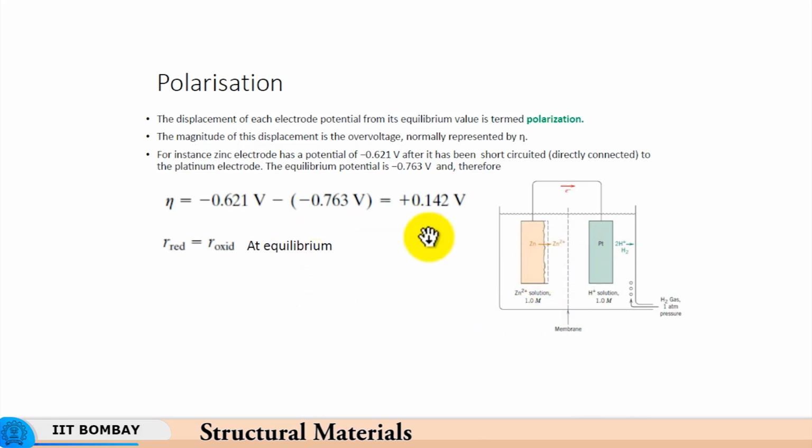So now here you have a situation where oxidation and reduction are not in equilibrium, because at this particular electrode, unlike the previous case, the zinc going into ions and zinc coming back are not in equilibrium. Therefore there is a net reaction between zinc and this electrode, so that zinc is being lost continuously, zinc is being corroded out from here.